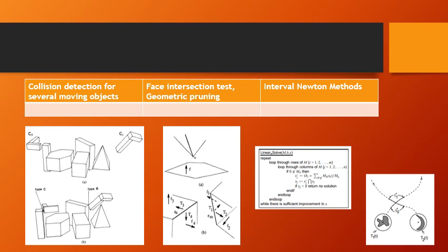There exist two different types of contact. In type A contact, for a given relative orientation between two polyhedra, it is for the vertex of one and the face of another. For type B contact, for the relative orientation between two polyhedra, it is the contact edge of one and the edge of another. In order to refine the intervals towards the solutions of the collision constraint, methods of computing are discovered using quasi-Moore form, interval inverse and matrix iteration in the interval linear equation solution algorithm. This computes the interval Newton step.